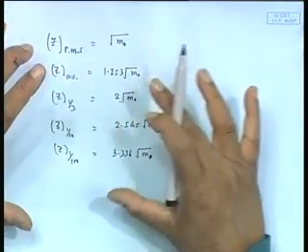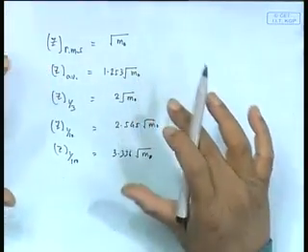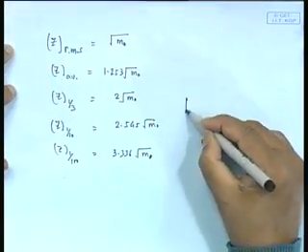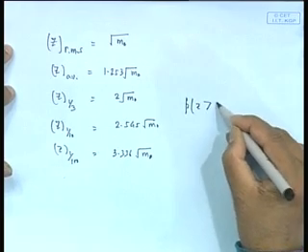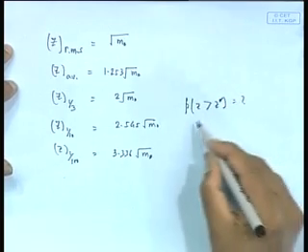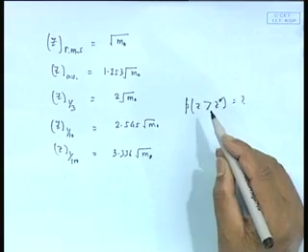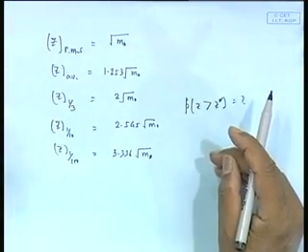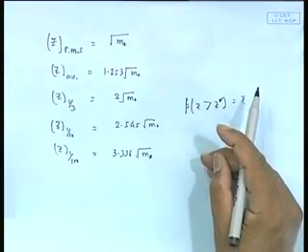Not only that, because it is a narrowband spectrum, you can also find out the probability of z exceeding, for example, z star. What is the probability of z remaining within this bound? What is the highest z you would encounter in 100 cycles or 1000 cycles? What is the chance of h becoming more than 0.1%? Any quantity of interest is available because the same formulas will apply. Obviously, people do not go for all of them.